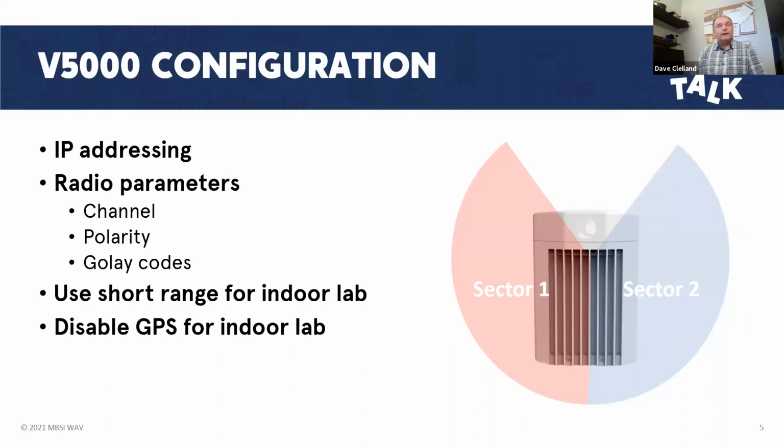And then we tried to connect it together, and lo and behold, it wouldn't work. So why wouldn't it work? It was because of the azimuths. At 60 gigahertz, even with beamforming operating on the system, the azimuths are still pretty critical.